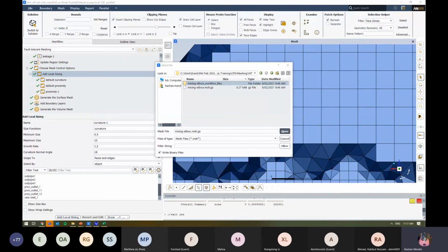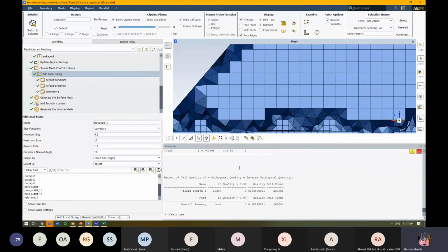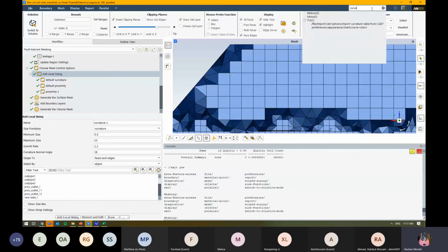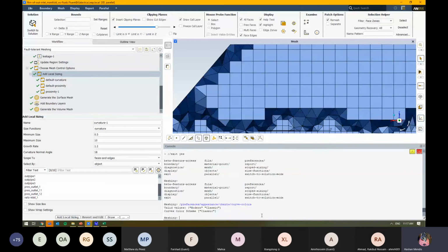Scripting language for Ansys and Fluent. So the Ansys and Fluent, by the way, is using just what's called the TUI, this text user interface. So everything we can do over here, if I actually select the console and hit enter, you can see all the functions that we've got there. Generally, what I do if I want to do anything, if you can just do a bit of a search for it, and you've got your TUI commands there as well. The video goes through some of that stuff, and you can then start to create these commands and create a journal file out of it as well. So it's not Python, anything like that. It's its own kind of text user interface.